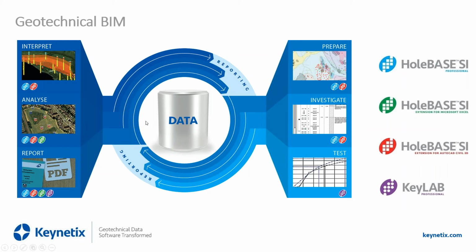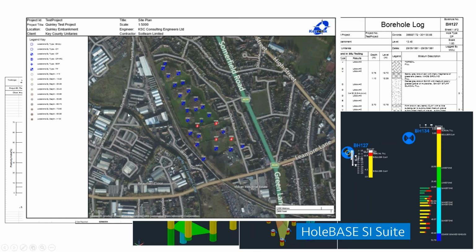And we also have a very similar tool that works inside Excel, so it allows you to visualize and understand your numeric data in Excel, which is actually stored and managed in HoleBASE. So these are the type of things that HoleBASE does. I mentioned to you, you can use it to plan where you want to put all your borings. Give this to your drilling teams, they go out and hopefully you'll get the data and your borehole data where you actually asked it to be drilled.